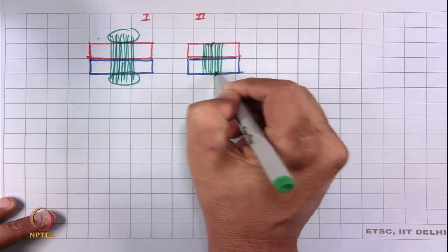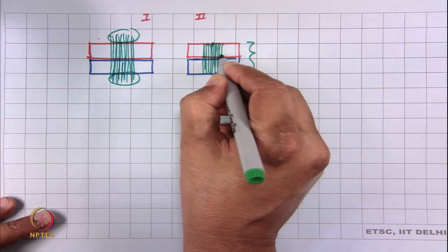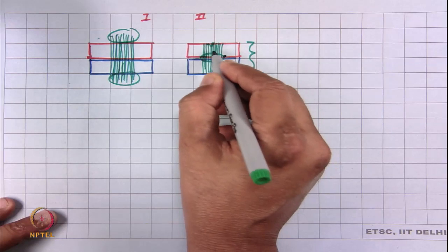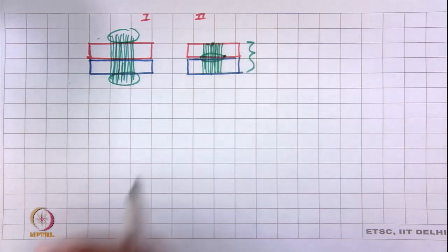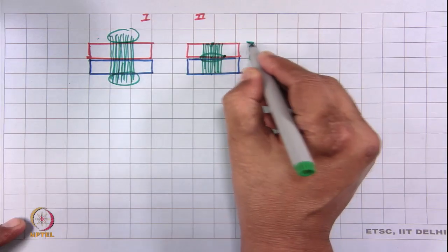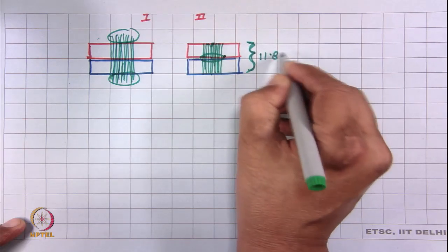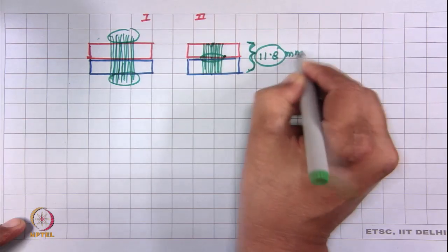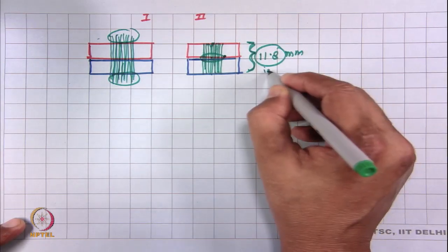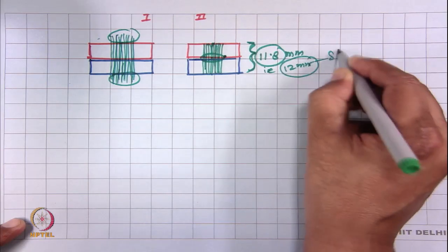These are the fibers. Now, this length, why 0 gauge length? There is no space between the fabric fiber, this is jaw. So, there is no gauge length, they are in contact, these two jaws. This length is typically around 11.8 millimeter, 11.78 millimeter, or approximately 12 millimeter. It is 12 millimeter in Stelometer.